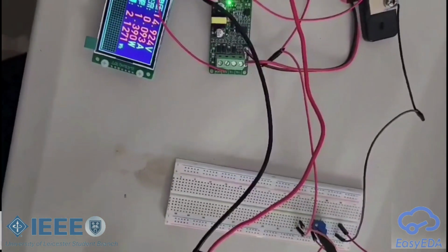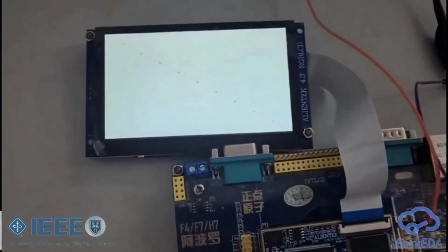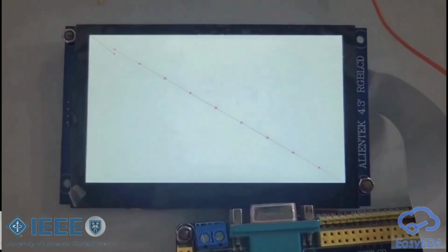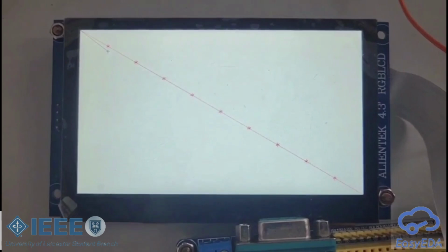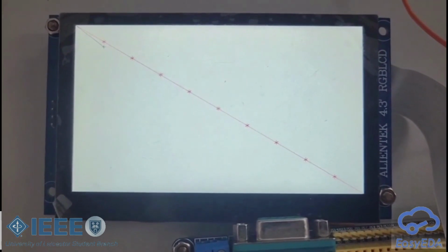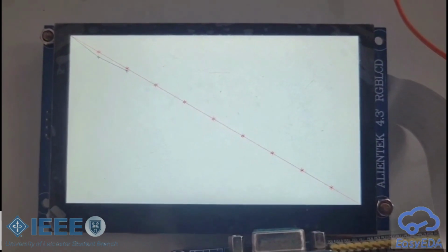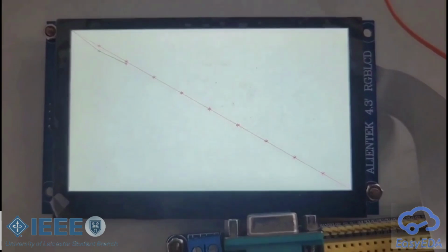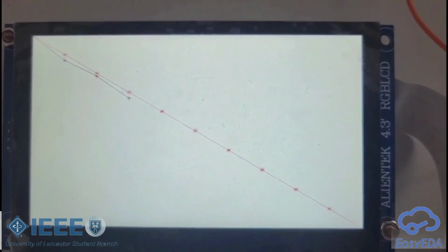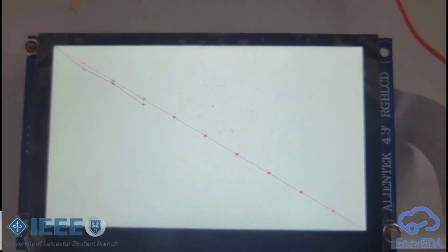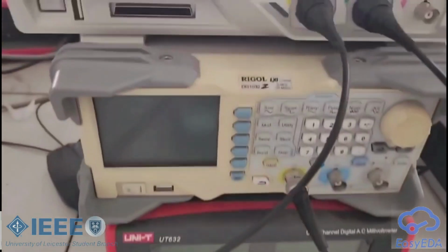In the video, the current is getting bigger. High power output means that the actual power consumption of the battery is too high. In the comparison chart, the remaining battery power is compared numerically with the points on the right ideal working state line. After comparing the images and obtaining the results, the microcontroller will adjust the output PWM signals to regulate the load speed, thereby making the power consumption closer to the ideal state.